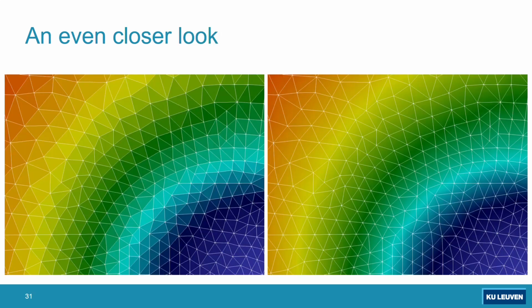But there is also another important thing here, the difference that you see between these two figures. As you can see, the one on the right is smoother. The reason is that on the left, each triangle has only one color, and on the right, you see gradients inside the elements. On the left, we can say that we actually solve the equations inside these elements, these triangles, and that's why each triangle has only one color, demonstrating the level of oxygen.